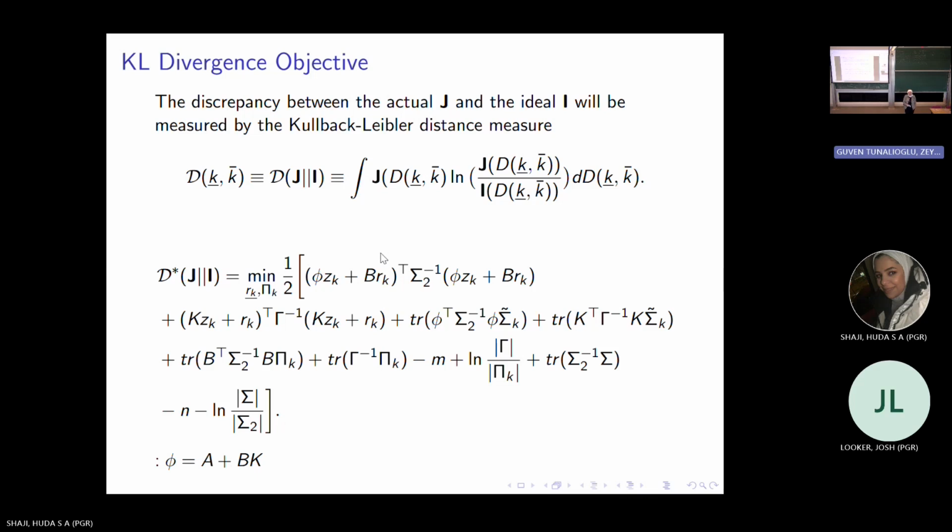Hopefully. Do you have any idea if this would work if it was a heavy-tailed distribution or something? Would you still expect it to work reasonably well, or would it go completely wrong? It will be a little bit modified. What I'm doing now with my supervisor is writing the general form for different distributions, not normal. After we write the general law, we'll check how we apply model-based control. Do we have the quadratic problem again, or maybe not quadratic? We'll check that. But now we have quadratic because we are depending on the normal distribution. Okay, thank you so much.